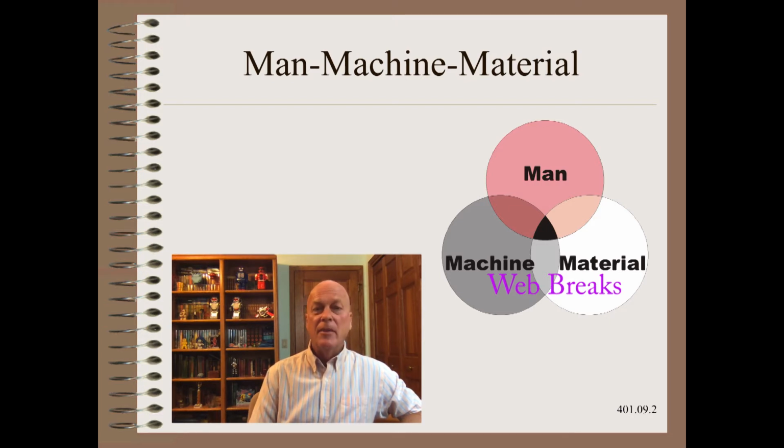Your material may be increasing break rates due to nominal design, such as average tensile strength, or variation in properties, such as cracks or holes near the edges. On the other hand, your customer may have a machine that greatly exacerbates the problem with poor tension control and poor roller alignment, for examples.